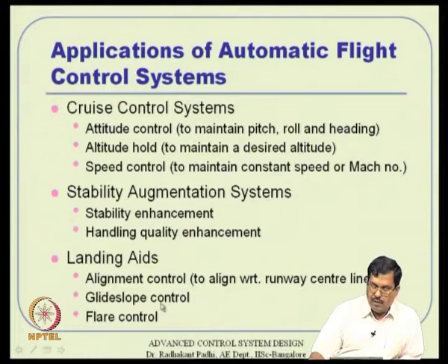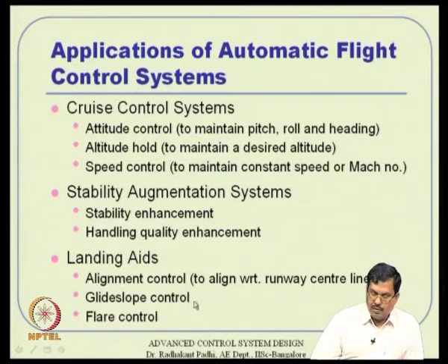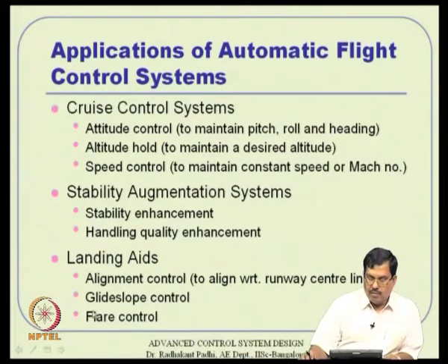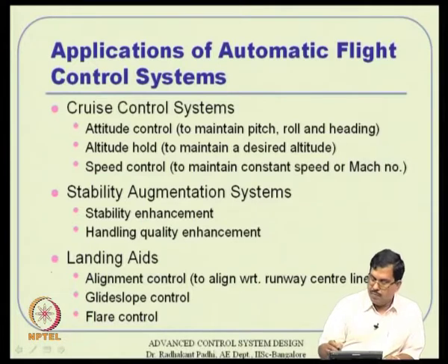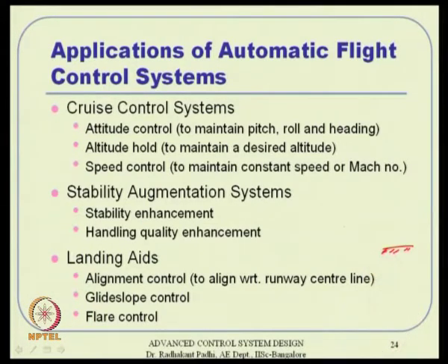Number two is it needs to have some sort of a glide slope control, that means it has to continuously decrease its altitude from its cruise condition to almost 0 height with respect to the airport runway height. Okay. And then there is also something called flare control. I will touch upon it a little bit as we go along, but roughly speaking, after alignment happens, suppose this is the runway, then the aircraft should come roughly in a straight line, that is called glide slope, and then it should flare up, in the sense that after that it cannot just go in a straight line, and if it does, then it will hit the ground in a very bad way. So, what is done is once the aircraft is very close to the runway, they excite some sort of an exponential path actually. Okay. So that while it touches the runway, the vertical component of the velocity is manageable actually. So, this part is called flare and this part is called glide slope actually. This is flare, okay, and this is glide slope.